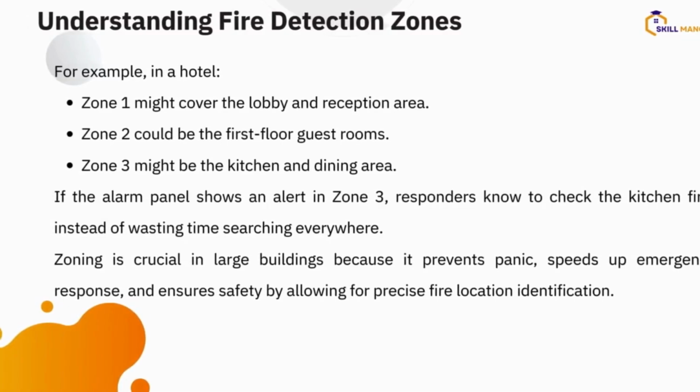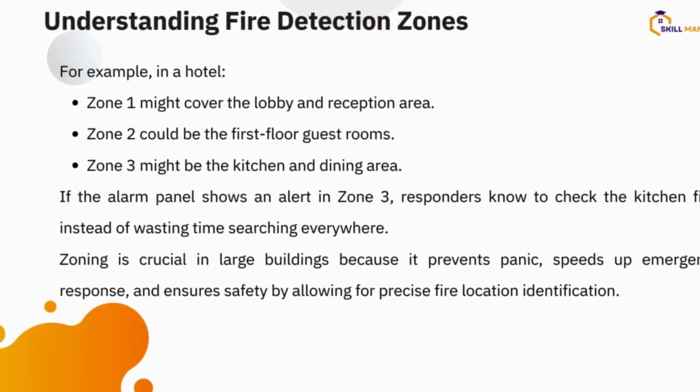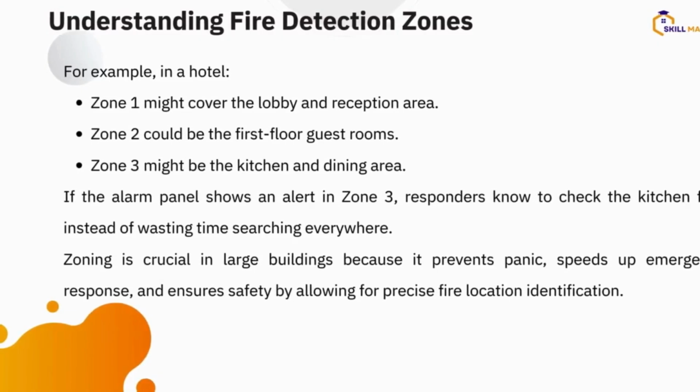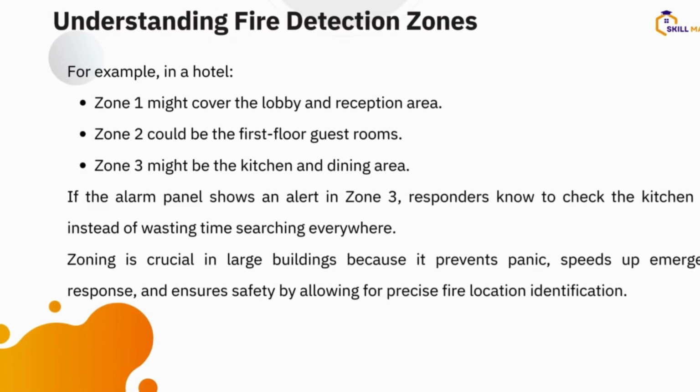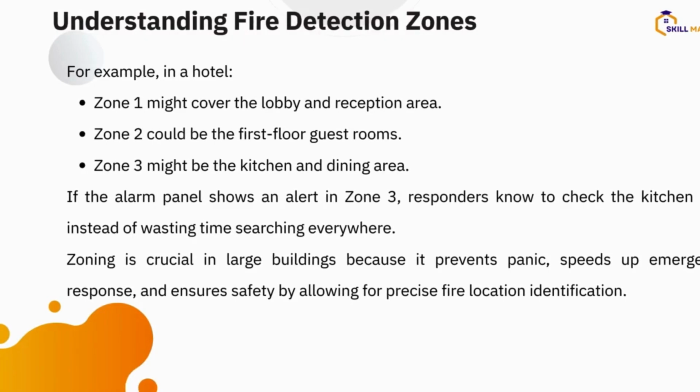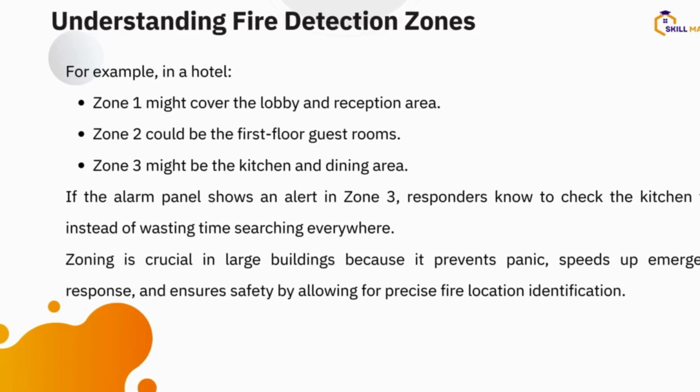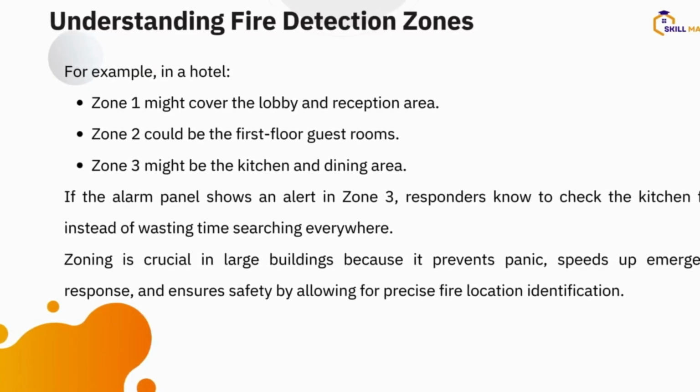You get a building now, a complex. They want you to put fire alarm as an integrator, as an installer, as an expert. You have to zone the building. Oh, this area is close, I'll put it on zone one. This other area, they are close to each other. They are nearby. They're easily connected. Zone two. The next one, zone three, zone four.